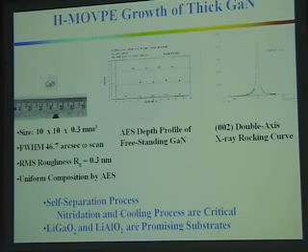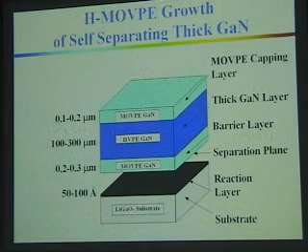Turns out, too, when you take a look at the gallium nitride and the separated lithium gallate, it's separated at the gallium nitride oxynitride interface. So the substrate is completely reusable. And you just keep growing, self-separate, put it back in, grow again. The material had about a 50 arc second full width half max, which again is high quality material. The composition was very uniform by Auger. Again, as I told you, we got very smooth results in the surface, and we also got a more thermally stable material if we grew this capping MOCVD layer.